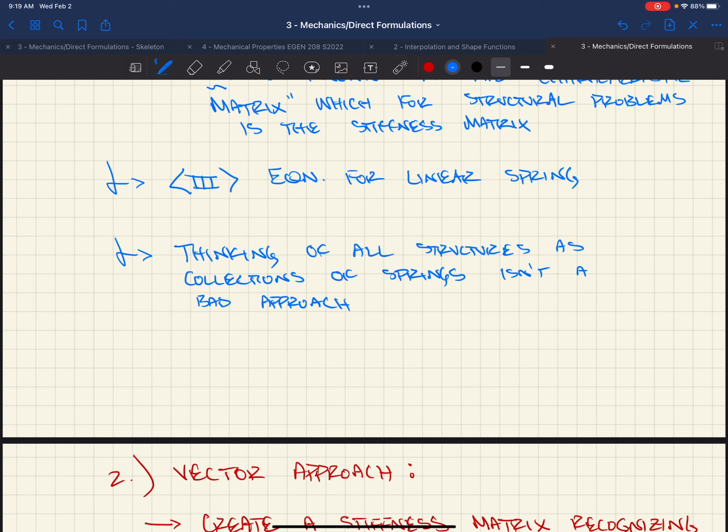After looking at it from a stiffness perspective, we had this huge, massive diaphragm, this big deep beam supported by 10-inch thick concrete walls on all the perimeter of the building. That was way stiffer than the brace frame extending below, the one that went from roof level to basement level. Just a weird phenomenon that happens, but it's all based on stiffness.